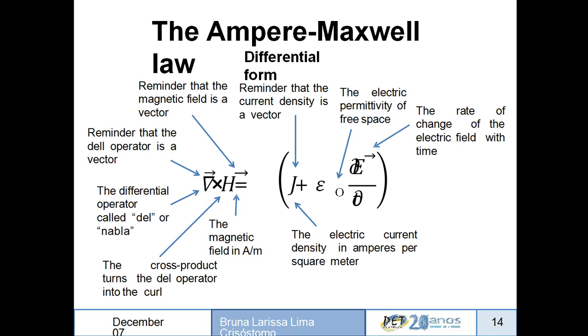So as we know, the magnetomotive force is the closed integral of H dot dl, which is equal to I. Now I is nothing but the surface integral of the conduction current density over an infinitesimally small area. If we take the surface integral of the dot product J dot dA, we get the total current enclosed by that surface, and that will be equal to the closed path integral of H dot dl.